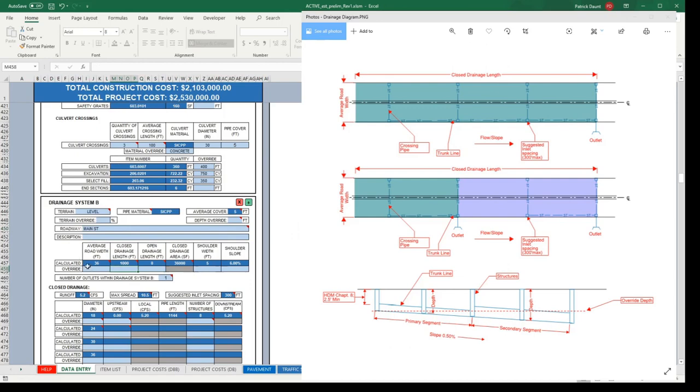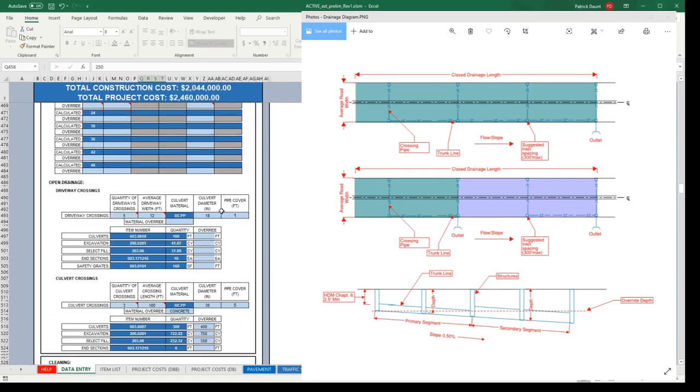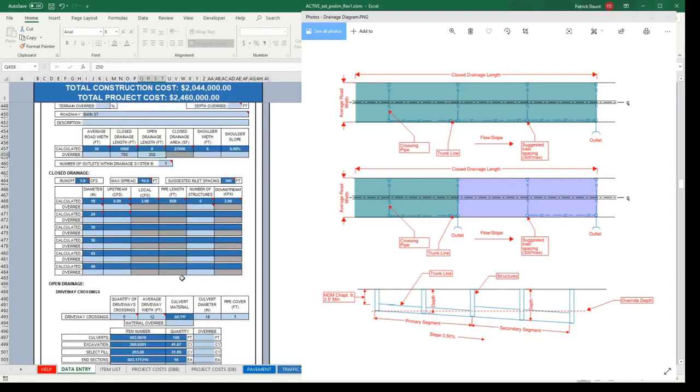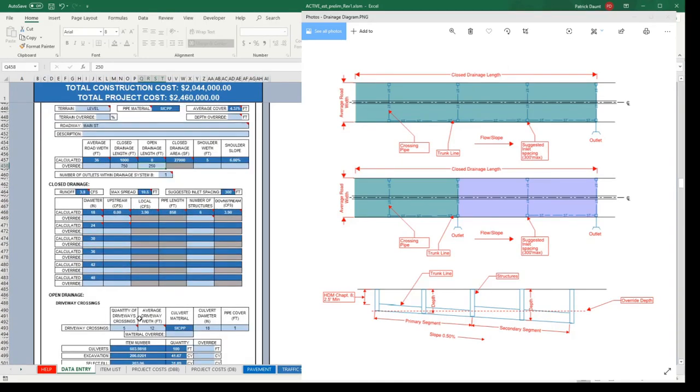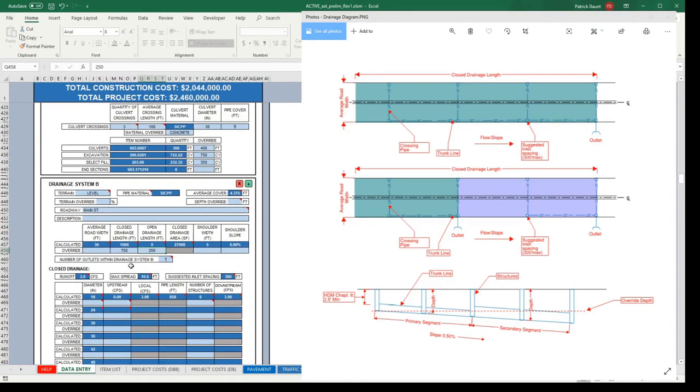Let's, for the heck of it, override this to be 750 feet. So we know, for instance, that if there's 750 feet worth of curbed road, the remaining 250 is considered open drainage. This value doesn't really do much further downstream. It actually used to populate and calculate in here, but during our user suggestions and testing phase, we found that it wasn't very helpful.